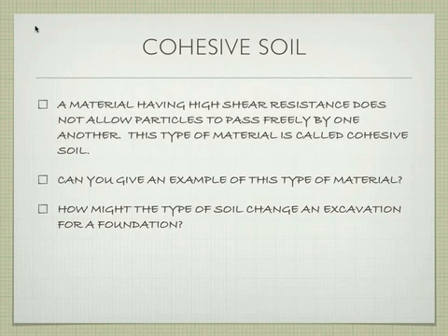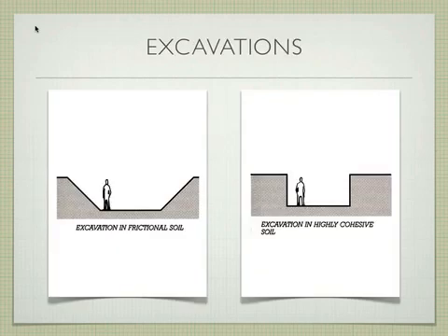Cohesive soil is a lot easier to dig out because it keeps the shape after you dig it out. Whereas with sand, for example, you start digging and it starts caving in. Bingo. Dead on. Okay? So this is going to change the way we have to excavate a particular site a great deal. If, for example, you go out to the beach and you dig a hole, it's going to be really hard to dig a hole with perfectly straight sides. This isn't going to work because the sides are always going to want to slough back in.